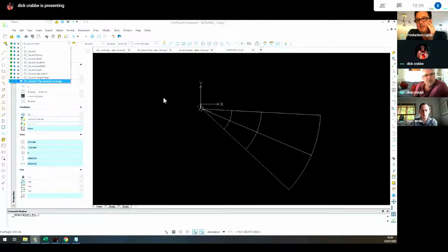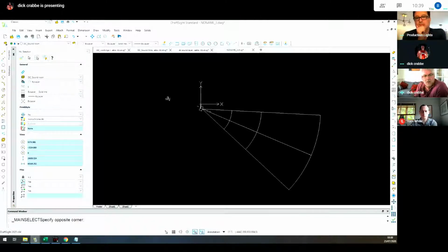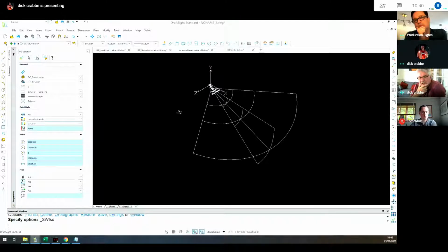It does seem to work for me. And so you bring them in once at a known location, put the frame onto the loudspeaker, and then the workflow that I've been doing is you put the first loudspeaker in the place that you want it to go, decide its pan and tilt, and then you either copy it or you use the pattern control and get the computer to put them where you want them, and that does give me the ability to see it in the dimensions and to be able to reasonably accurately say, combined with the plan and experience, here's the angle of tilt, the angle of pan that you want, which you can then.